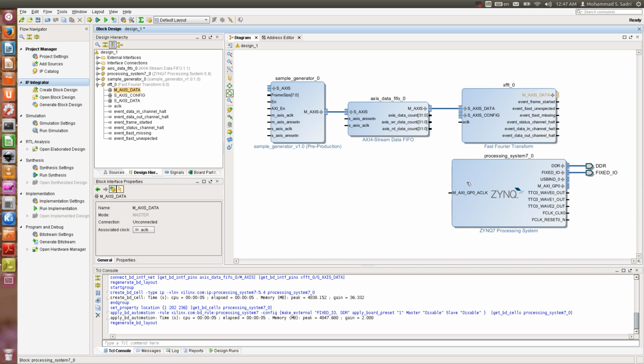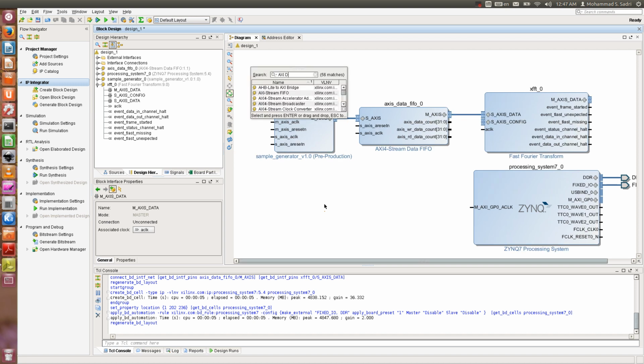How do we do that? There is a module, and indeed a set of modules, which perform this operation for us. Here I use the AXI DMA. So AXI DMA, not central direct memory access. Central direct memory access is not for now, it is something else. It is only memory mapped, I don't need it. What I need is AXI direct memory access.